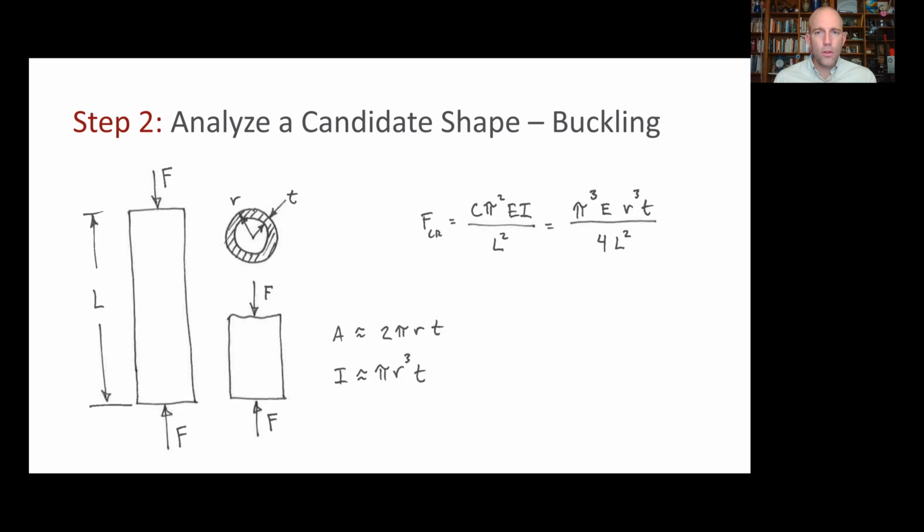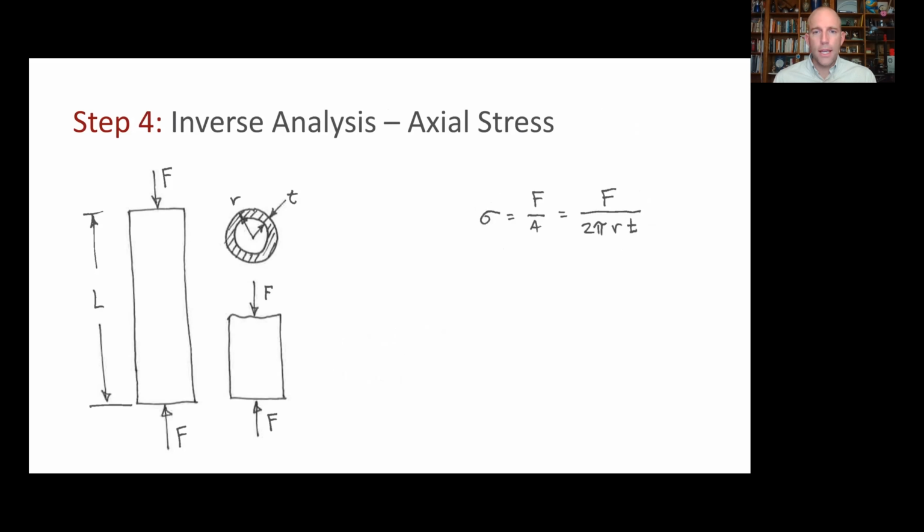Okay, now we'll invert these. And the idea here is that we're going to substitute in something for stress to get exactly our factor of safety, and then solve for one of the geometric parameters. And we're going to pick a parameter for which the mass will uniformly increase as it increases. And the simpler the relationship, usually the better. So do some substitutions and then manipulate things, do that independently, compare with your partner, and come back. Hit pause now.